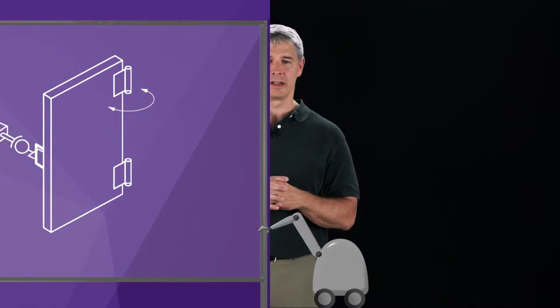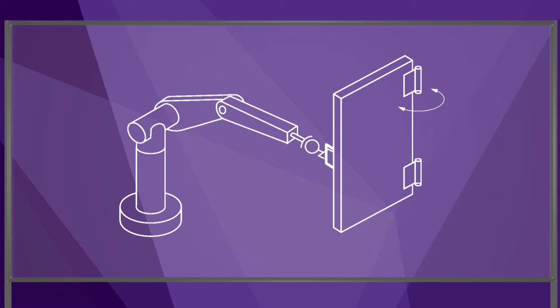In the previous video, I described force control, where the robot is capable of generating an end effector wrench in any direction, as if it's buried in concrete. This is rarely the case though. Typically there are some directions the end effector can move freely. In this video, we assume that the robot interacts with an environment consisting of rigid constraints, and the control objective is hybrid motion force control, to control the motion in some directions and the forces in others. An example is opening a door.